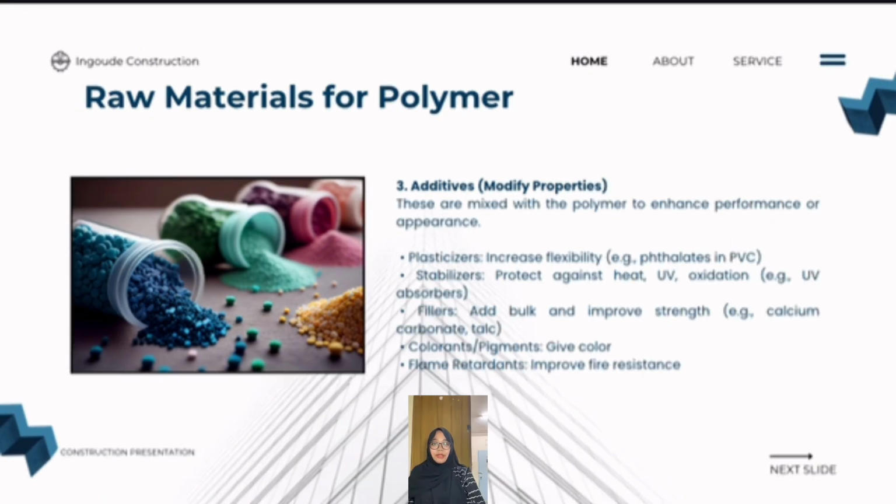To give polymers desired characteristics, additives are introduced. These include plasticizers for flexibility, stabilizers to prevent degradation, fillers to increase strength, and colorants for appearance.